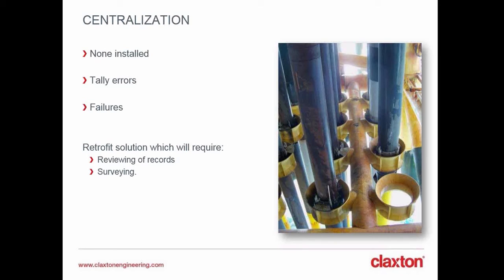There's also a big aspect to cover during the survey, which is not only the interfaces of the new unit with the existing equipment, but also how you are planning to install the equipment. In some of these cases, you're trying to carry out the work with just the facilities of the platform, so there might be limitations as to what you can or cannot do to solve the problem. So this needs to be considered during the survey. A good survey should comment on that installation and should tell you what preparation work needs to take place in advance so the operation can be carried out safely.